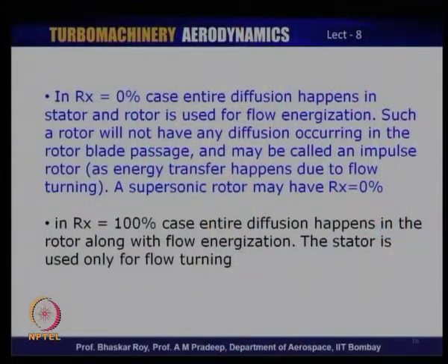If you have a reaction that is 0%, okay, a limit, the entire diffusion happens in the stator, and that means the rotor is not having any diffusion at all. Hence, the rotor is being used only for imparting work into the flow, energizing the flow, putting work into the passing flow, and such a rotor will not have any diffusion by design occurring in the rotor blade passage.